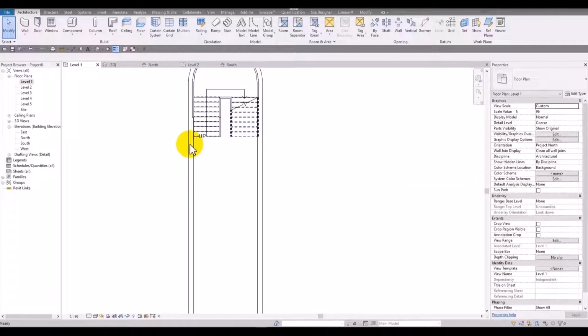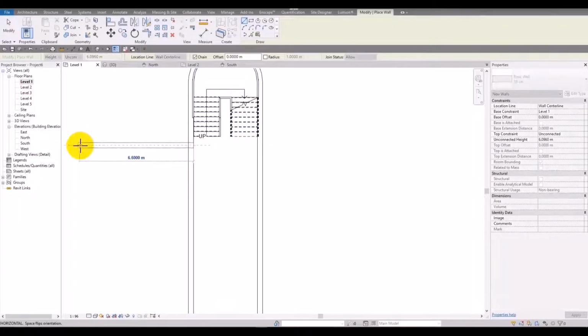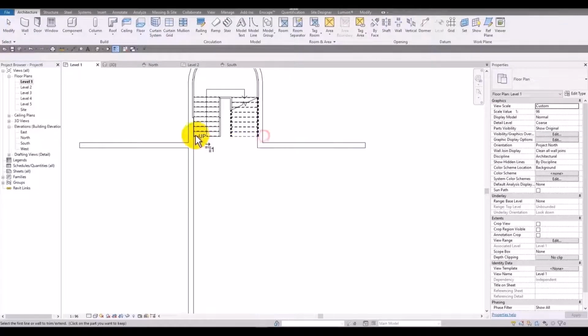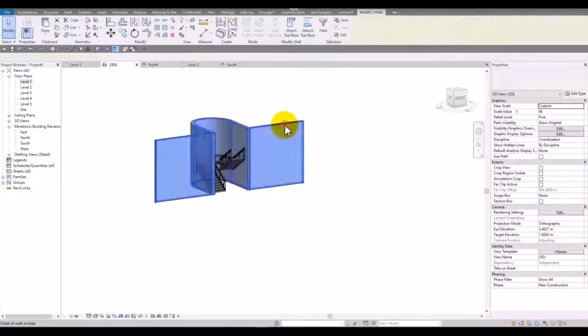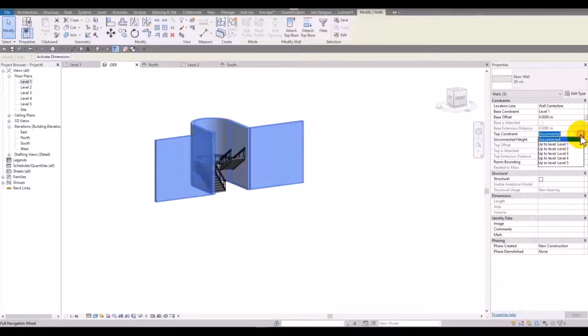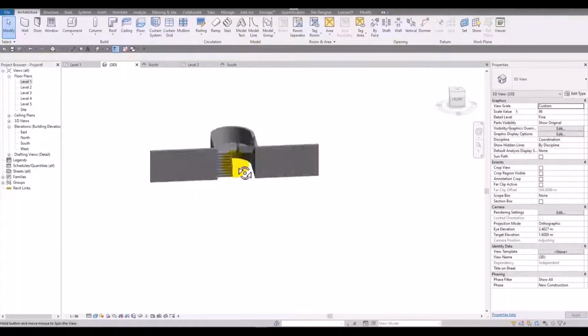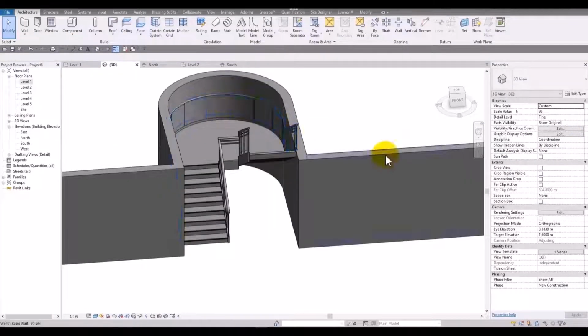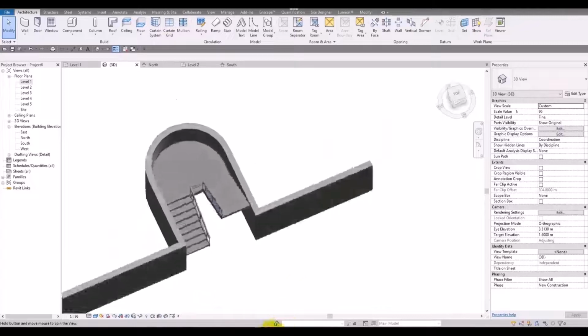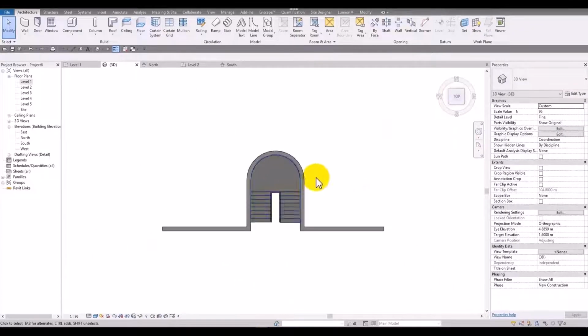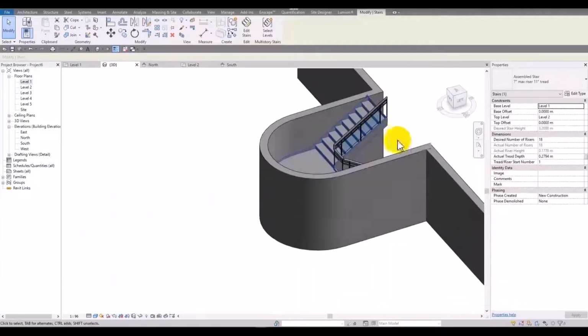Okay, we are still in drawing of the stair. We're not in settings yet. Okay, I do this like this, then I trim it, and this will be its shape. I select these walls. I want to have them till level 2. And here at this side we don't need the railings anymore. We can even remove the supports. But for now let's have it here like this.